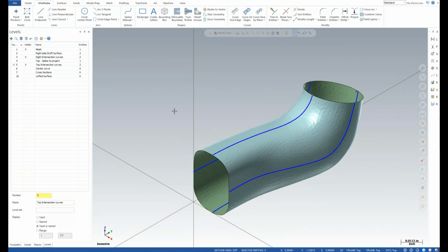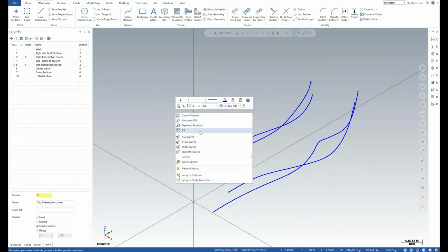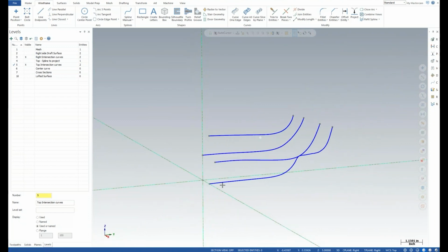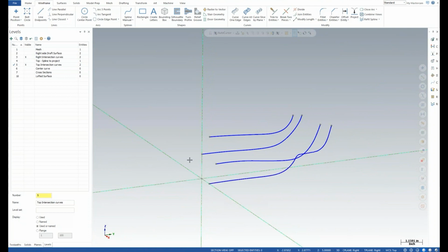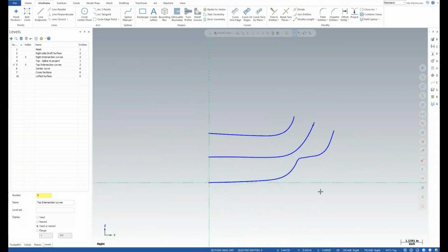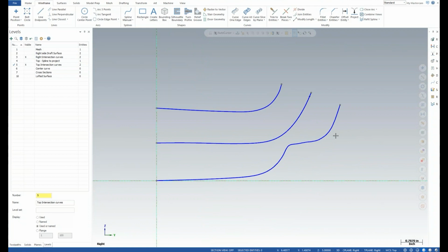to be machined. All right, at this point, I'm going to go ahead and turn off my mesh, and we're going to go look at it from the right side again. Now, I'm going to use these curves to create a center medial axis, a center medial curve, which is a new function inside of 2026. But before I do that, I want to take the hump out here because it's not necessarily necessary for what I'm trying to achieve.